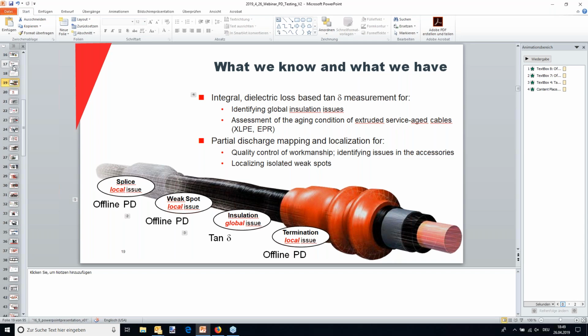So if you have a rubber mat or anything made out of a material that has a significant permittivity, you create a hotspot for the field lines there, because the field lines are compressed into the dielectric material and you create more corona. I know it sounds counterintuitive, but the best thing is always to bend the cable a little bit back and just have it suspended in air, with your sphere of 20 centimeters around it so you don't get much influence. That's really the best way to have the cable.